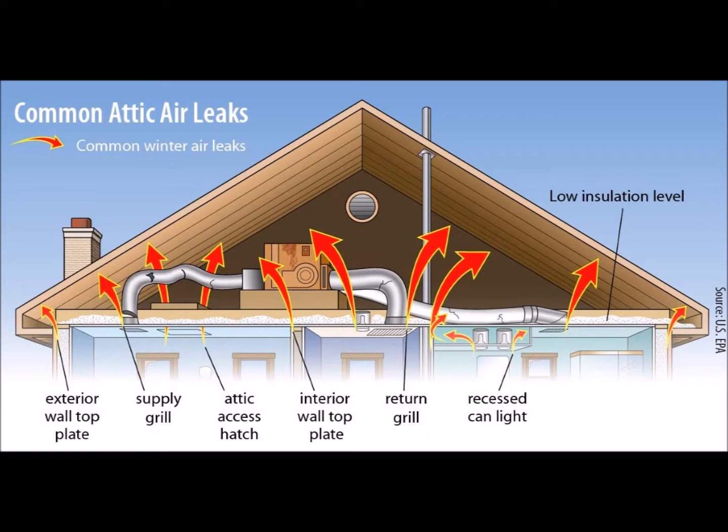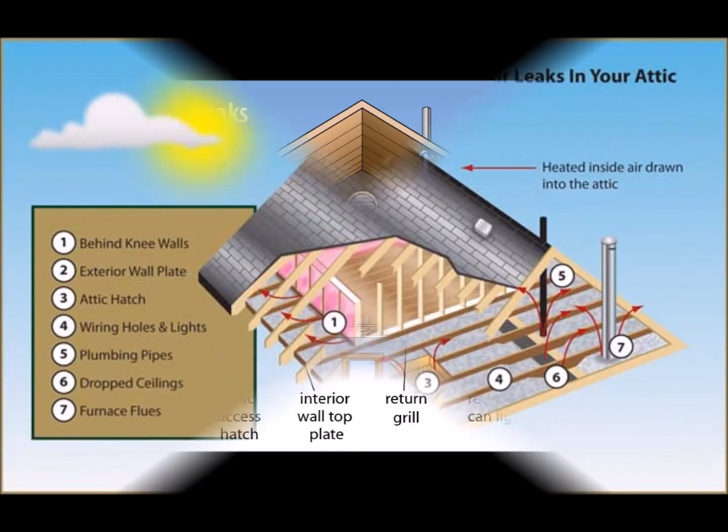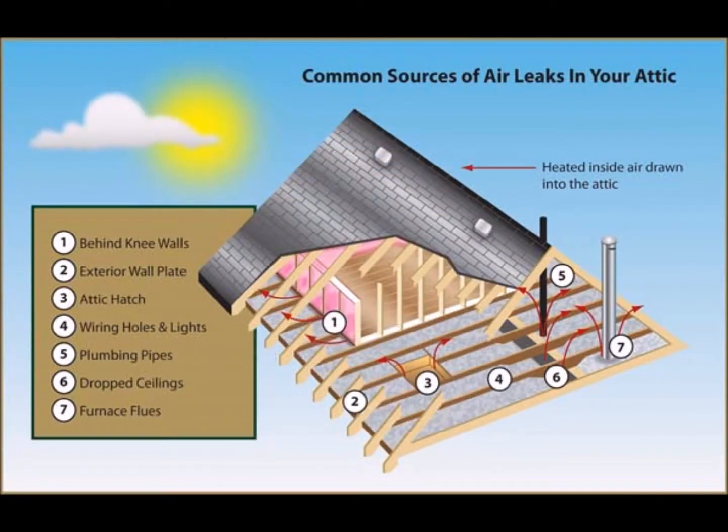There are some special considerations when dealing with cathedral roofs as well as air leaks. Cathedral roofs can hide roof water leaks as well as condensation, particularly if a vapor diffusion retarder, such as poly sheeting, is used on the ceiling side, something that should be considered only in very cold climates.